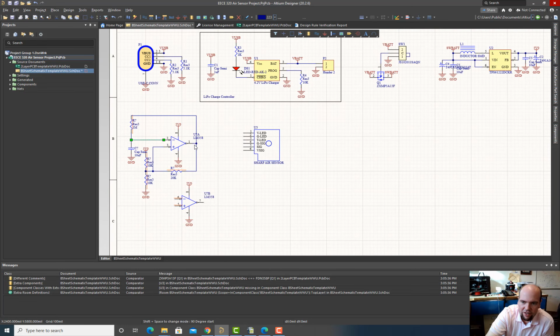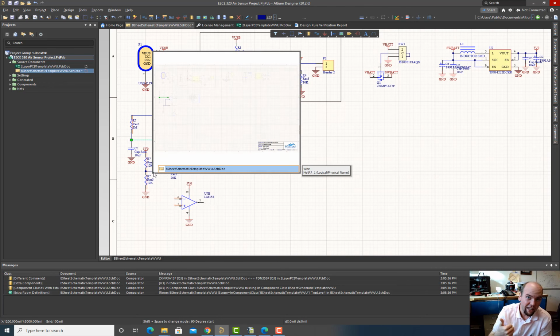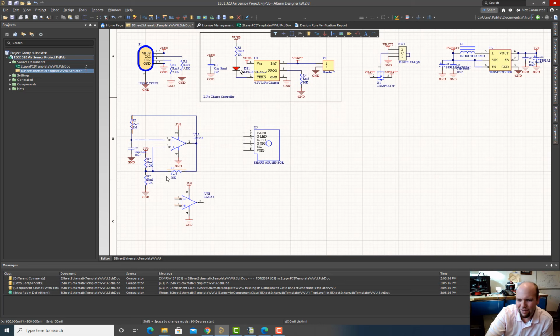But there's also the output of the op amp through this 20 kilo ohm resistor, which is able to pull this voltage a little bit higher or a little bit lower. So it can pull it a little higher than 2.5 or a little lower than 2.5. And I think it ends up being something like 2 volts to 3 volts. It can shift about half a volt around. You can do the divider if you want to see exactly what it is.